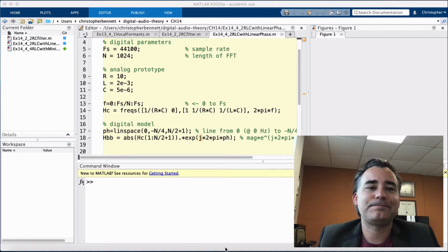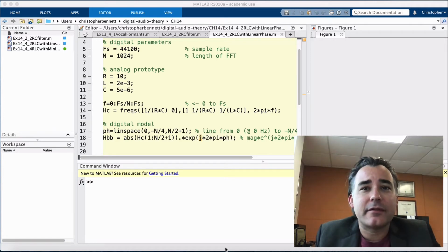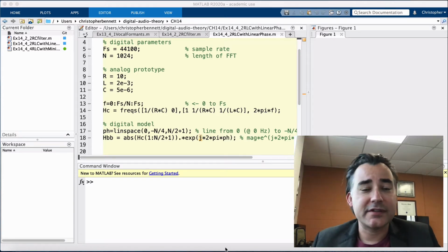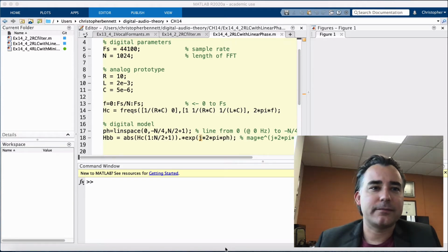a digital filter. Now, frequency sampling is the method of capturing the magnitude of the desired frequency response and constructing a digital filter by assuming either linear phase or minimum phase. So this should tell you that this is going to be an FIR filter.